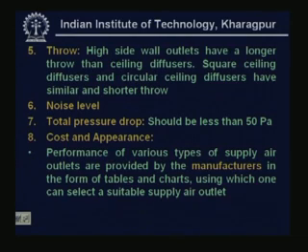So the manufacturers, after thorough testing, publish their catalogs, where they normally specify the characteristics of supply air outlets in terms of the flow rates, throw, pressure drop, and noise criteria, etc. So depending upon the requirement and using these catalogs, one can select the required type of outlet, and depending upon the area or the flow rate requirement, one can decide the number of outlets. Okay.